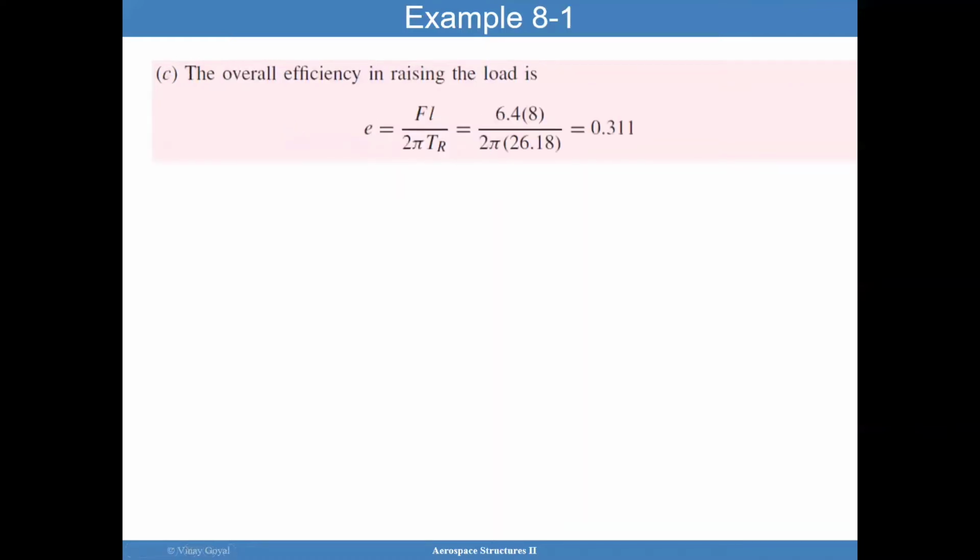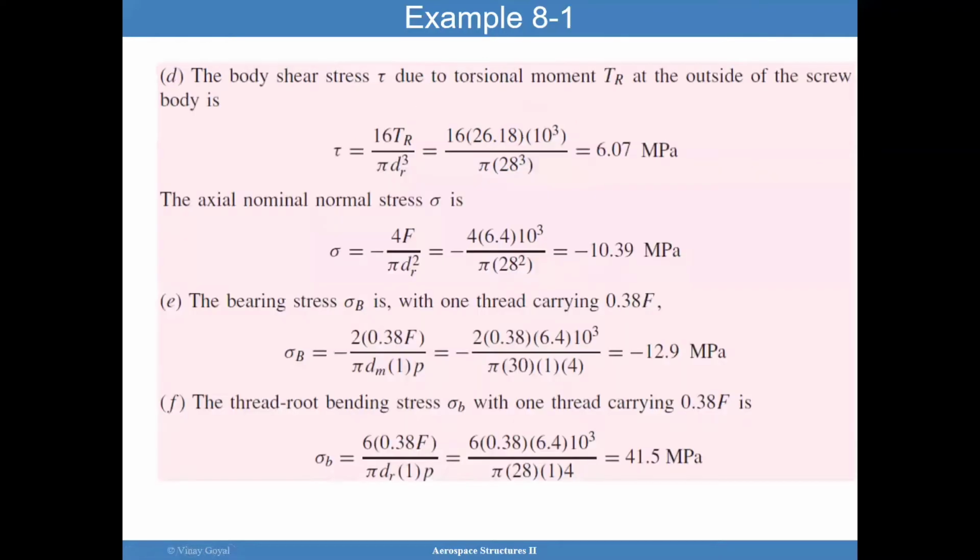And then you can actually calculate efficiency by assuming a friction coefficient of 0 for the numerator, and then divide that by the torque to raise. And this shows you that the overall efficiency in raising the load is about 30%.